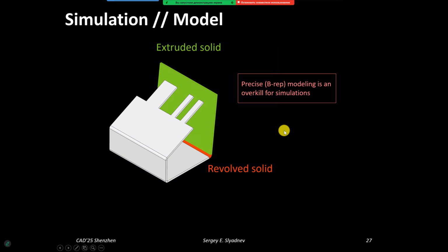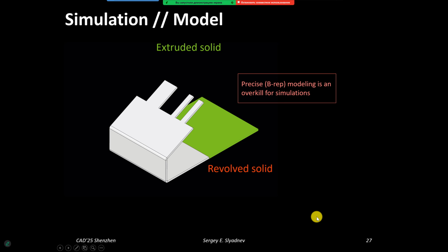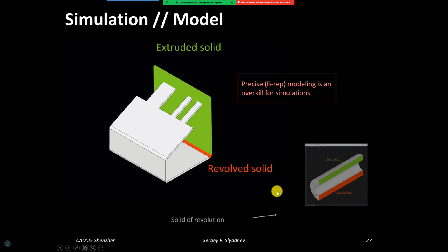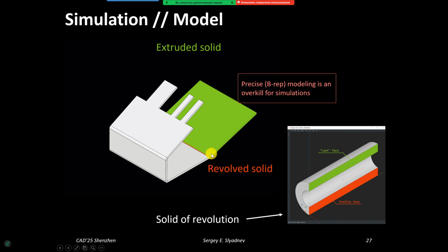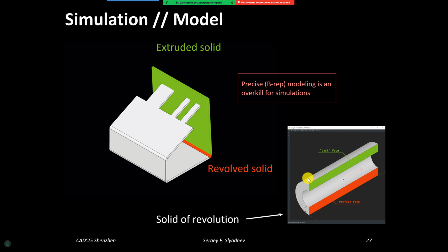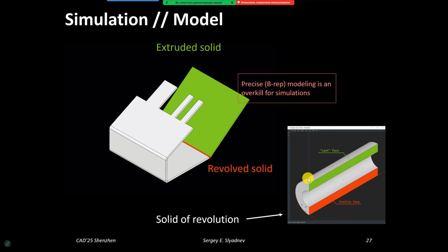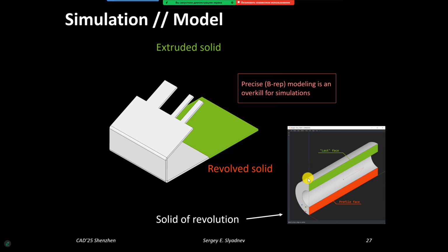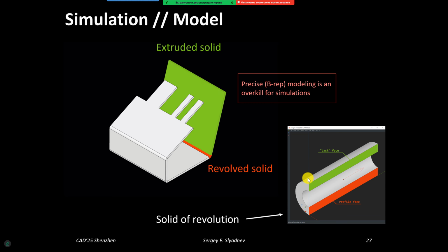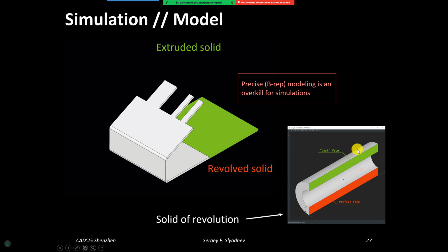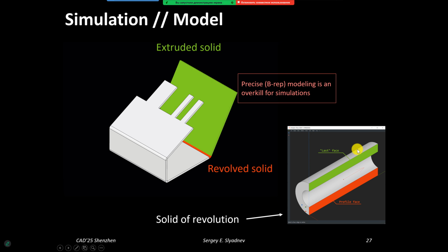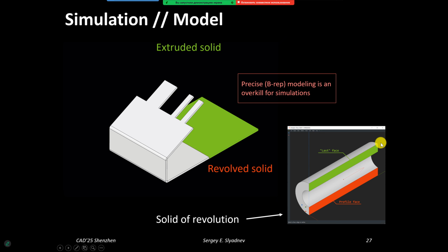You rotate the rest of the part, the flanges that you want to fold or unfold, and you build another solid of revolution for another bend angle. But this modeling technique, although it might give you very precise modeling results at each intermediate state of geometry, is pretty computationally heavy because at each iteration we go for accuracy, so we model for precision. That's not exactly necessary if you want just to simulate collisions.